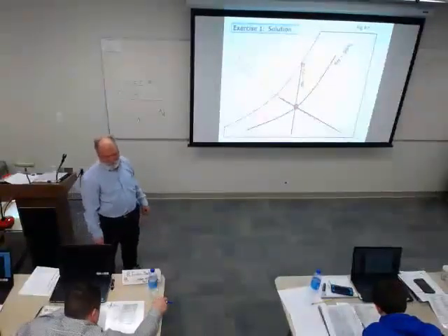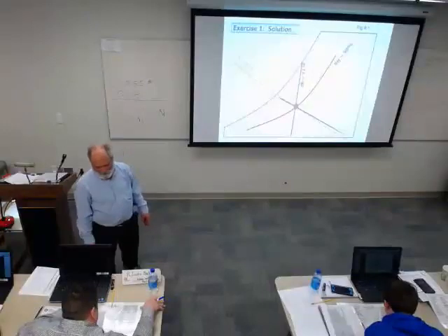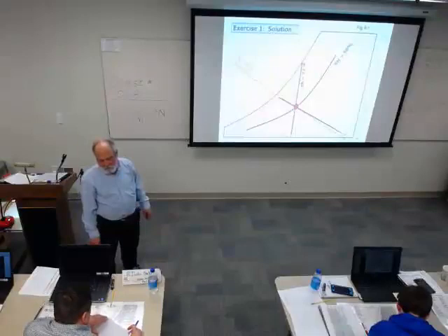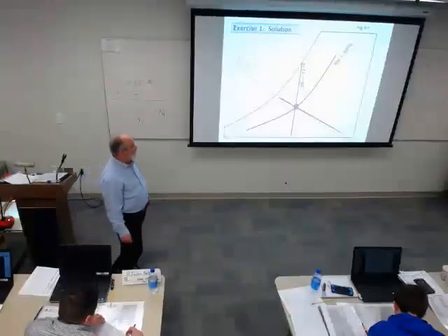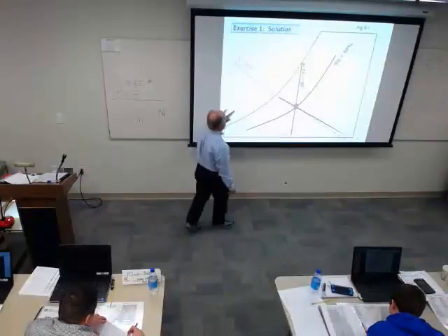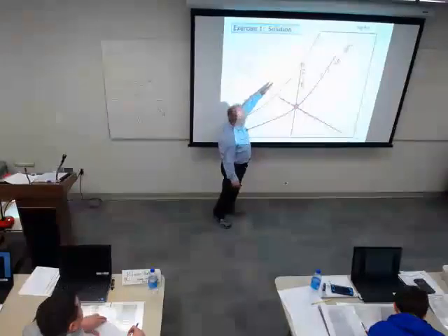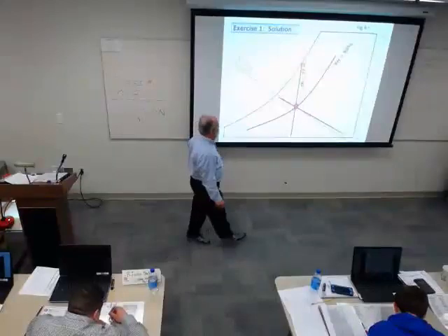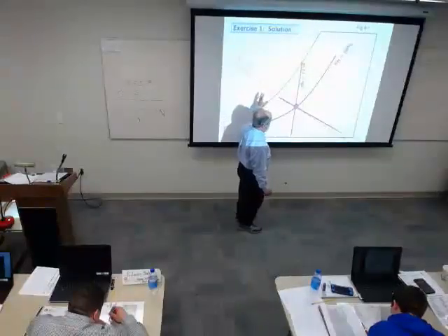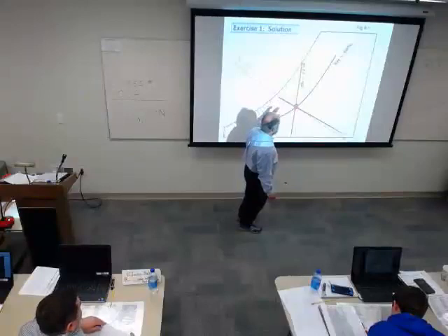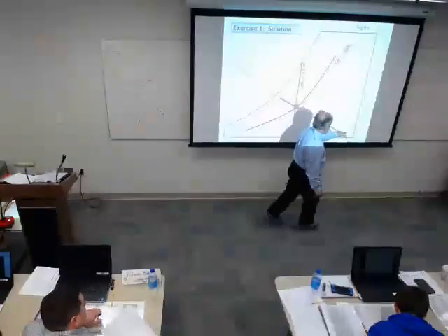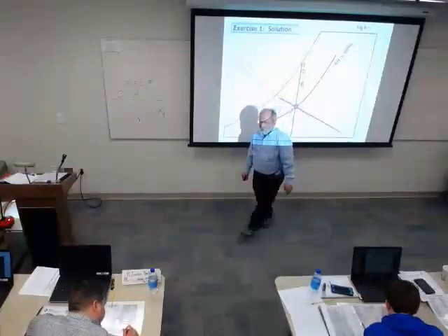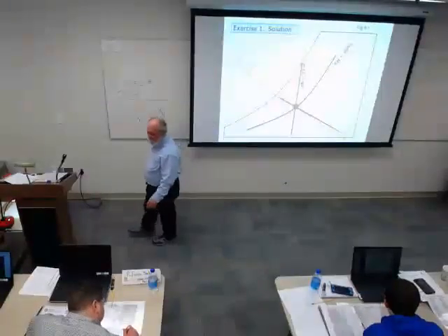We're gonna cheat on this. So what you do is you line up a piece of paper or something with that circle, and you've got the line along. In this case, our enthalpy lines are nice enough, they're straight out here. And on the other side, there's going to be an enthalpy reading, or whatever chart reading, that matches this. We'll get over here somewhere, because in this case it's down here somewhere. And it's kind of nice to have an idea about where you're looking.